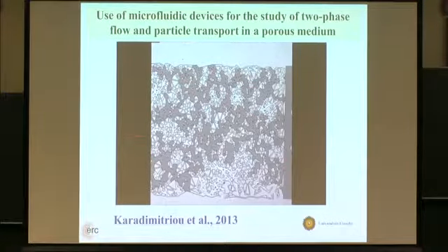Now, at some point, we can reverse the process. This is called drainage: the wetting phase is displaced by the non-wetting phase. And then when we put the wetting phase back in, that's called imbibition. It's imbibed into it. And what you see here is that the movement of the black phase, the dark color, will not occur if these interfaces between the two liquids don't move.